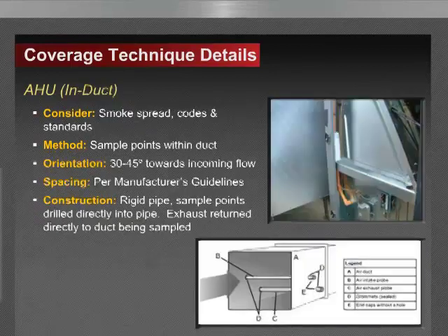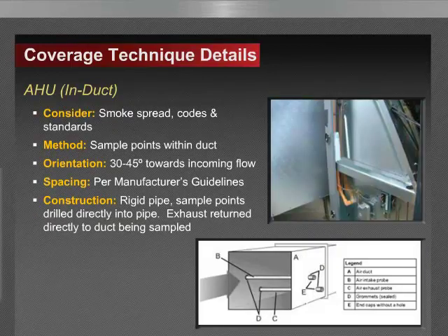In a fire event, ventilation duct systems can convey smoke, usually hot toxic gases and flames, from one area to another. Duct systems may also supply air to aid combustion in the fire location. Therefore, the effective management of smoke control, such as dampers and shutters to contain smoke spread and fire growth, is essential for life safety and asset protection. In-duct sampling is accomplished by installing a dedicated aspirating smoke detector and inserting specially configured 3/4 inch rigid sampling pipe and exhaust pipe into the duct, and of course carefully following manufacturer's guidelines in doing so.